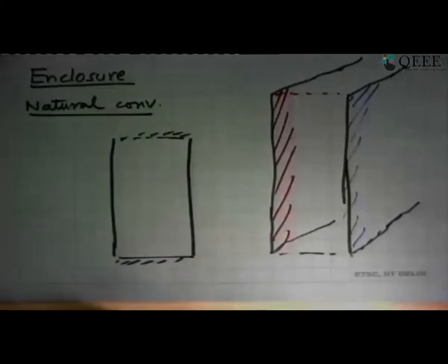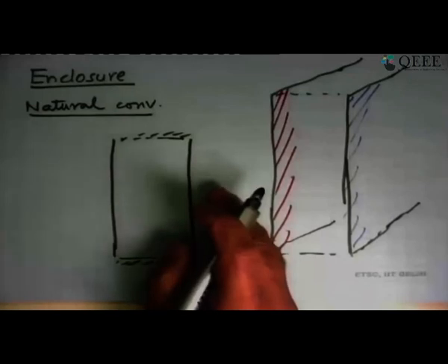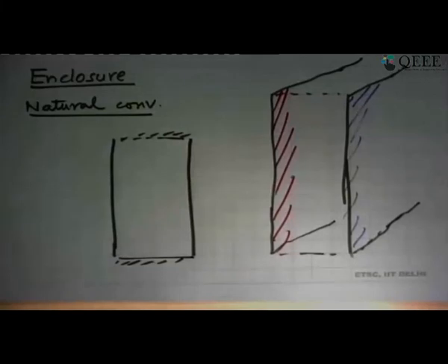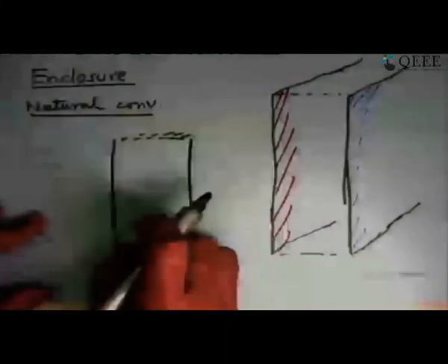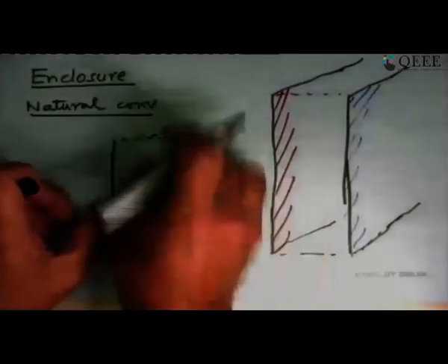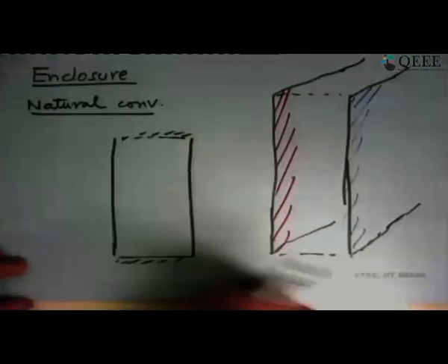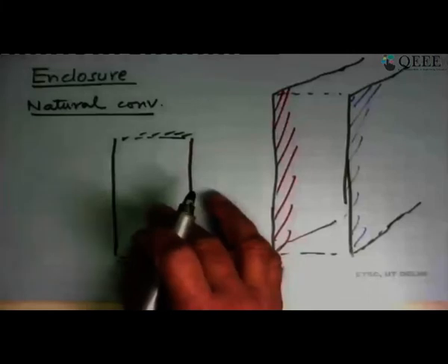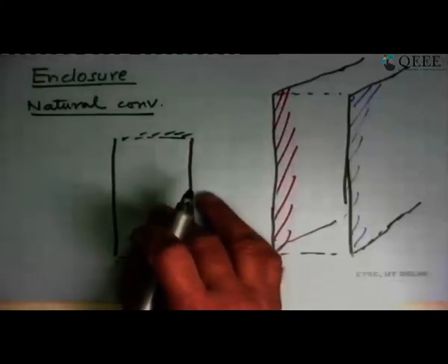Where do we get a practical example of this? Well, this is there in buildings. If you want to maintain cold temperature, you just give a small gap between two parts of, say, a wall, the inside wall and an outer wall with a small air gap in it, and this gives a very good thermal insulation because in between now you have air. So this is a solid there, this is a solid, you have a small air gap in between. The thermal conductivity of air is very, very poor. So if you have only air in natural convection, it's an extremely good insulator.